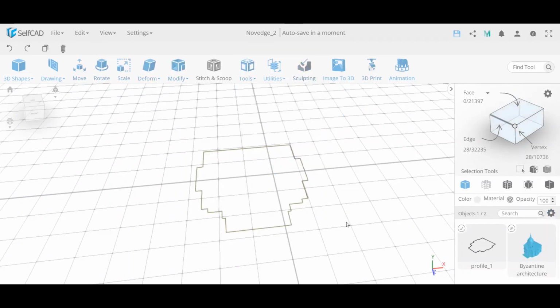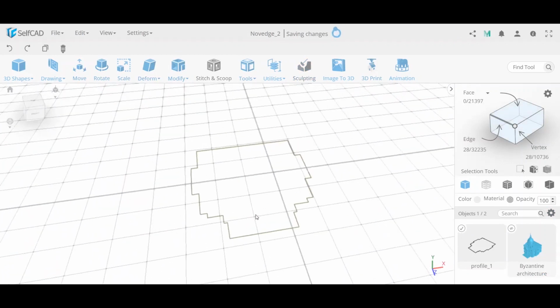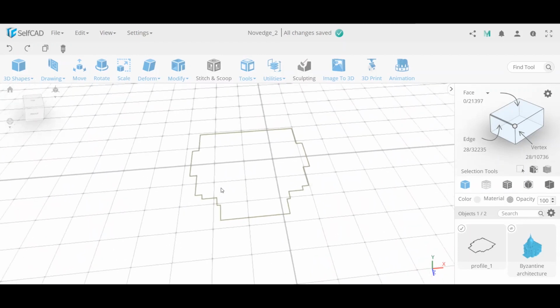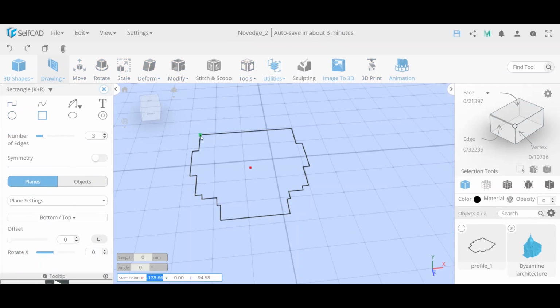Okay. And I want to show if you draw something like this, as I said, you need to have the measurements. So for now, I can use this. So I don't need to measure again, but just show the idea of how something like this could be drawn. So if you go to 3D Sketch, let me deselect this so I make a new profile. The basic idea would be you start drawing just a line and start turning. And if you want to make it in such a way, start drawing lines, one line, then start turning and so on.